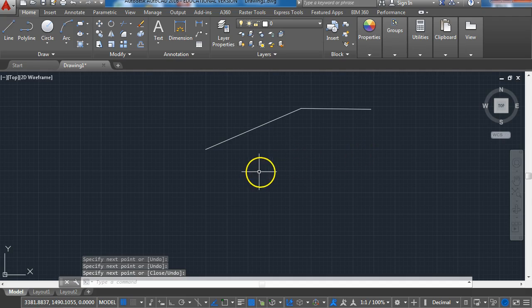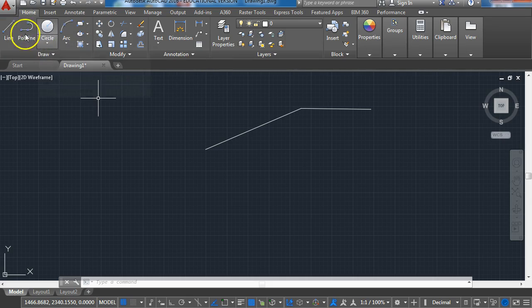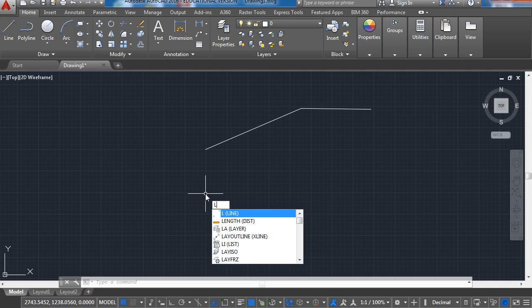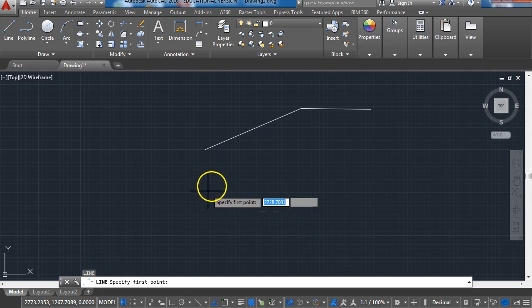Another way of entering the command, because if you're moving from your workspace up to your line tool or your draw tool buttons at the top here, we're using lots of mileage there. So what I encourage students to do is use the keyboard shortcuts. L is the keyboard shortcut for the line tool. So if you touch L on the keyboard and press either the space bar or enter. I use the space bar because it's easy just to have your thumb on the space bar and then use your fingers on the keyboard. So L and space bar, that'll enter us into the line tool.